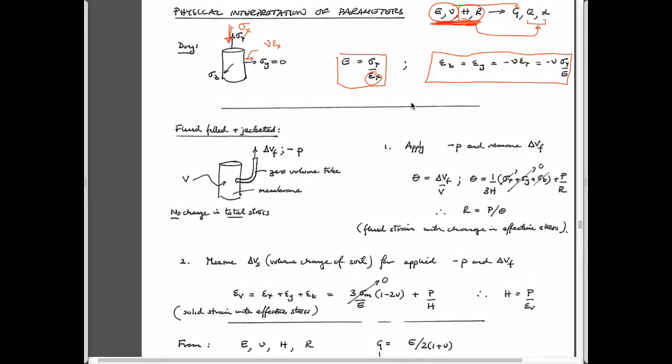We know, for instance, that if you load something, it develops fluid pressures initially when you load it. When those fluid pressures are dissipated, the behavior of that system should be exactly the same as if it doesn't have fluid in it at all, right? Because the pressures have changed initially, but they've gone back to their original condition, and therefore there should be no influence of that. So this understanding is important to be able to understand the long-term compression behavior. So that's useful. What happens if we take the sample and fill it up with water?